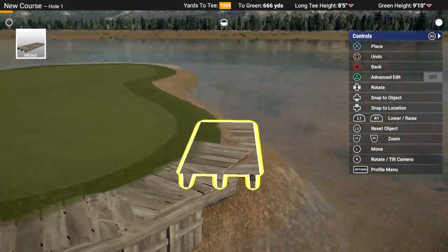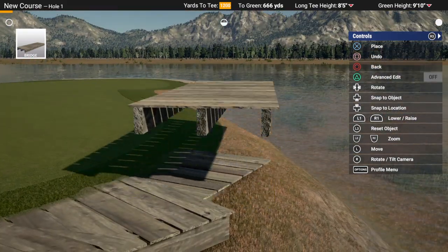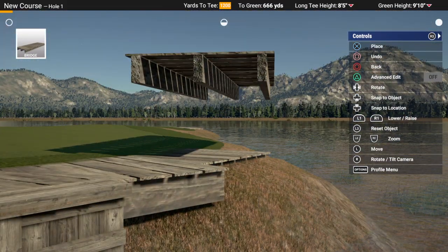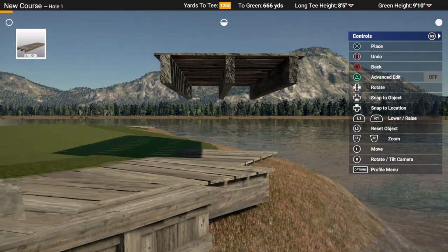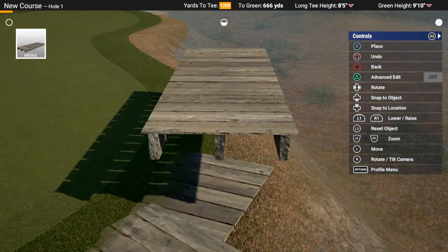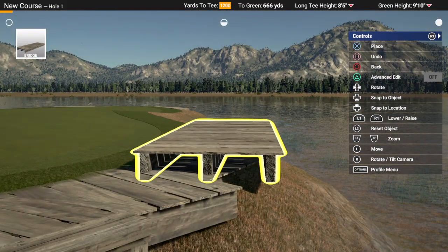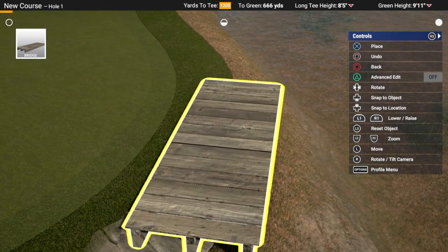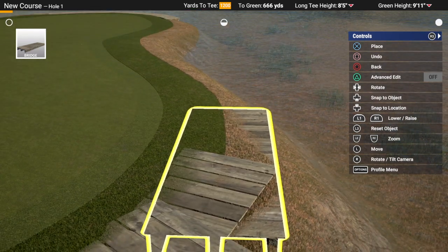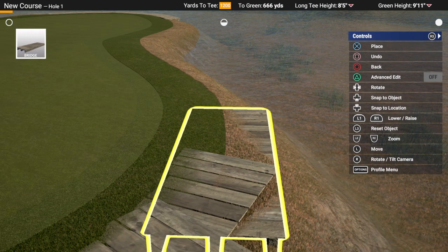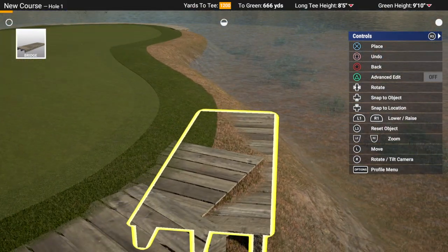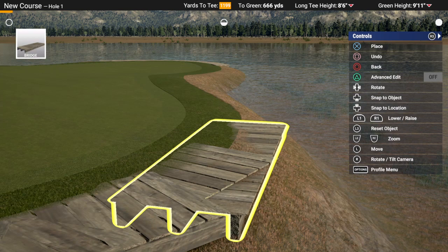And the key to get this lined up for me is, if we bring this up, you see how you've got the horizontal surface, but underneath you've got these three cross members. They're the bridge supports. For my alignment's sake, I'm trying to get that middle cross member in line with where my light rough ends here, because in my mind that's where I'm going to bring this wall in. So it's a good measuring line while I do this.